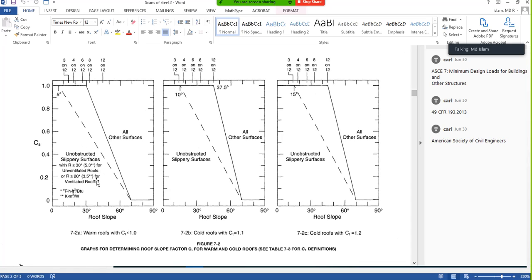It means if your roof is a very slippery type, that means it is not shingle; if you use another kind of material, I forgot the name. If it is the shingle that we commonly use in our buildings, the black asphalt type shingle, it is this other category. If you use a smooth type surface, then it is the slippery category. So mostly you will use this category. If it is 30 degree, go up, and you can see here it is 1. If it is 45 something, 60, come here, 0.2. If your slope is high, the coefficient is less because all the snow will slide.